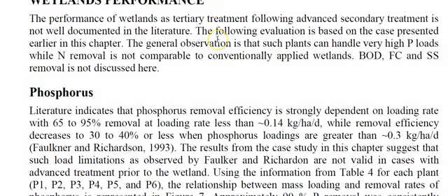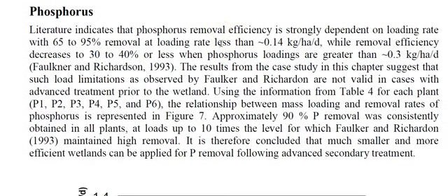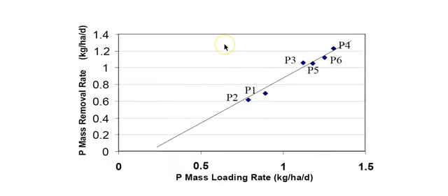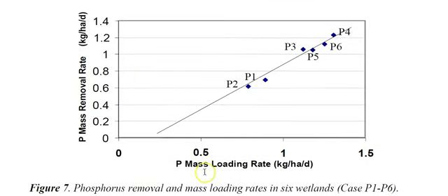Now then, a little bit about the wetlands, how they perform, phosphorus removal. It says in the literature that it's really dependent on the loading rate, and it certainly is. But what we also see from previous publications is that they say you should not go higher loading rate than something down here. And we have tested much higher loading rates. The main reason we could do that is because we have the advanced treatment in advance, so that we remove most of the BOD.